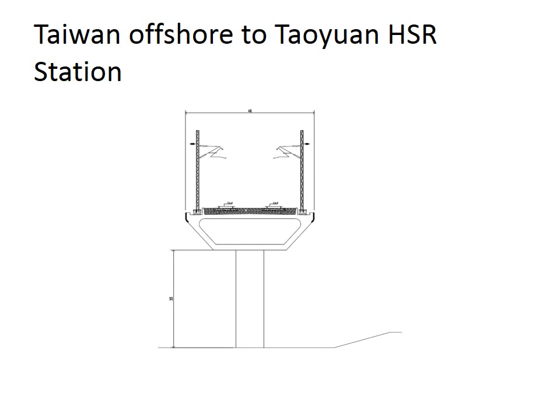And from Taiwan offshore to Taoyuan high-speed rail station, we majorly propose the viaduct to protect the environment, as well as to save some land acquisition issues. In Taiwan, the land acquisition cost is more, and the problems arising from the local villages are all severe in comparison with the Fuzhou area. And if we build a viaduct, this can advance the program as well as save some money.